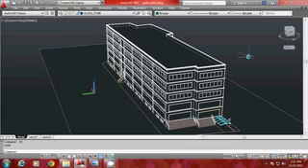So how do you make it? In a 3-point perspective, the camera and the target should be at different elevations, at different heights, and the line of sight should be inclined. So it is very easy to generate perspectives using AutoCAD software, and you have a lot of flexibility in controlling the position of the camera and certain parameters such as the focal length of the camera and the type of view, the type of perspective, etc.